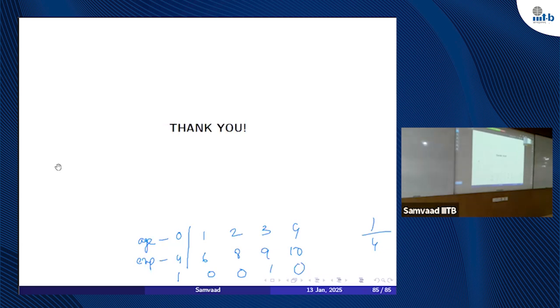Before you deploy the model on the FPGA, we have to quantize the weights a little bit. So what kind of quantization are you doing for, say, the perceptron model? We'll have to quantize those weights, right? Weight quantization. I am not quantizing the weights here because I'm taking fixed point, and these weights I'm storing in a lookup table. Let us say 0.49. All the values are normalized between 0 to 1. So 0.49, 0.3, like that. Whatever is after the decimal, I am storing that only in my lookup table. So I don't have to quantize.